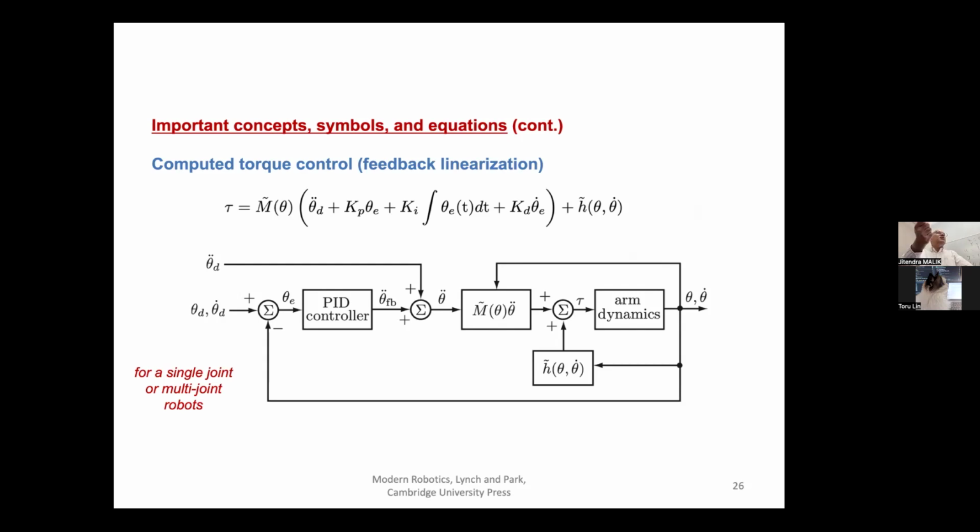So knowing the dynamics means that you know the mass of the link and things like that, right? So for your known robot, you know the masses of the links. It's all there in the URDF file, and you incorporate that. So you don't assume that all that is an unknown. And you also have a term which is measuring the error and feeding it back using the PID control. So you design a controller which has both of these aspects. And if you want, you can think of it as a combination of a feed forward and a feedback controller.